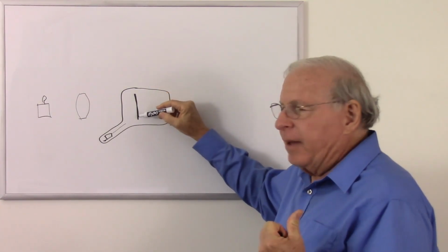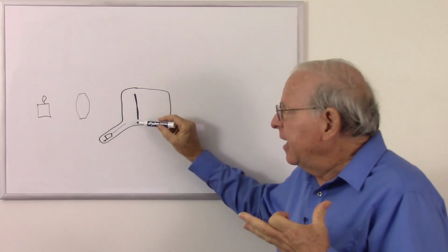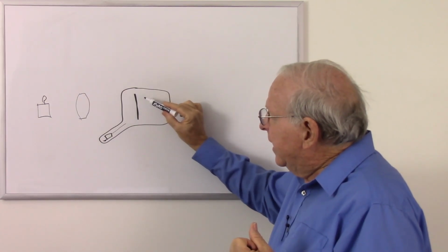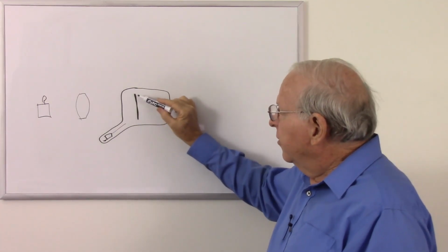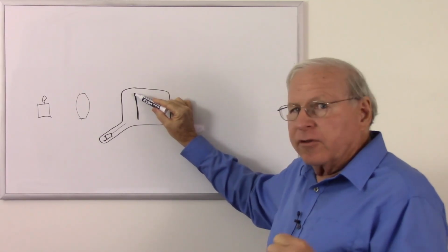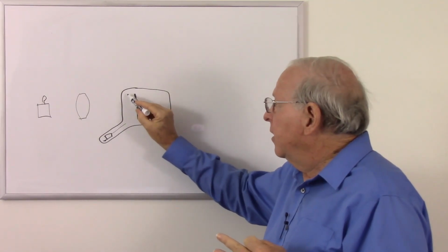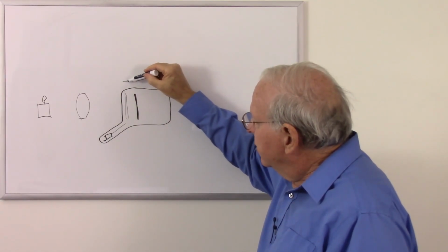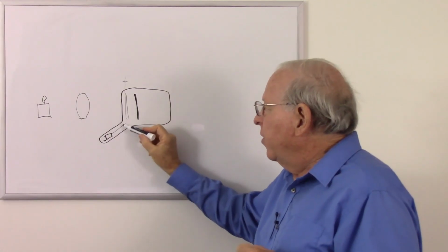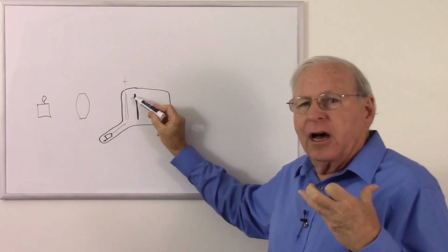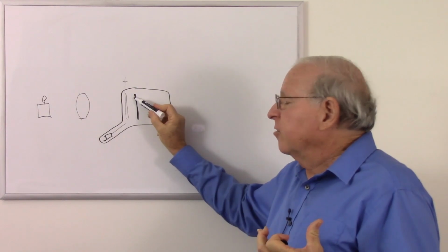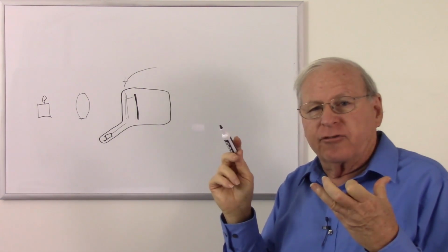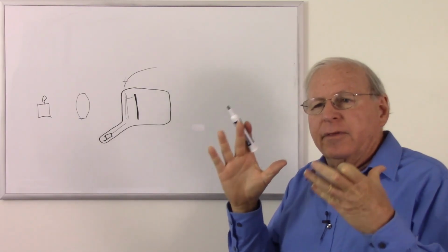So we had electrons on these capacitors, few electrons where a lot of light had hit, and more electrons where less light had hit. And then they would scan it again with low velocity electrons, and where there was a large charge here, those electrons would be repelled, and there was a ring of metal or something similar to that in the front that was positively charged that would attract those electrons away. So this beam comes and hits a place that had a high charge where little light had hit. Those electrons would be reflected away, picked up by this ring, and so we would have a lot of electrons reflected away where little light had hit.